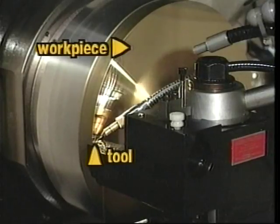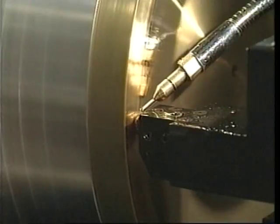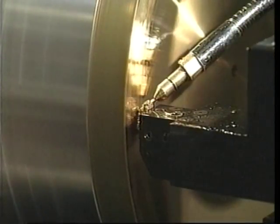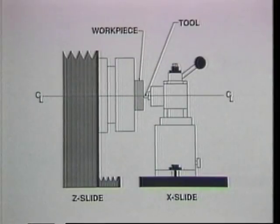By coordinating the relative motions of the tool and workpiece, flat, spherical, and aspherical surfaces of revolution can be generated. As seen in this illustration, the tool engages the workpiece at the horizontal centerline of the spindle. Therefore, the squareness of motion of the axes in that horizontal plane is the unknown to be determined.